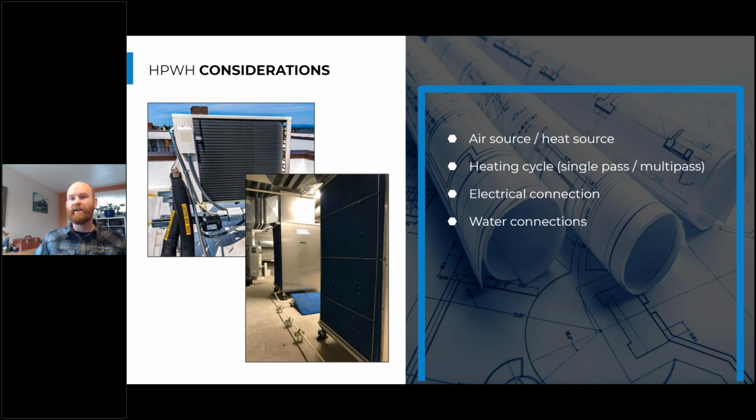The other thing that's super critical is our water connections, not only to our storage tanks, but to our heat pump water heaters. If these heat pump water heaters are located outside in Seattle, there's potential for that to freeze. So do we want to design in freeze protection, or are we going to super insulate the pipes, or does the heat pump manufacturer have some built-in control cycling to act as a freeze protection means? It's really critical that we understand our water connections and whether freeze protection or other measures are required so that we don't have issues on our cold days of the year.